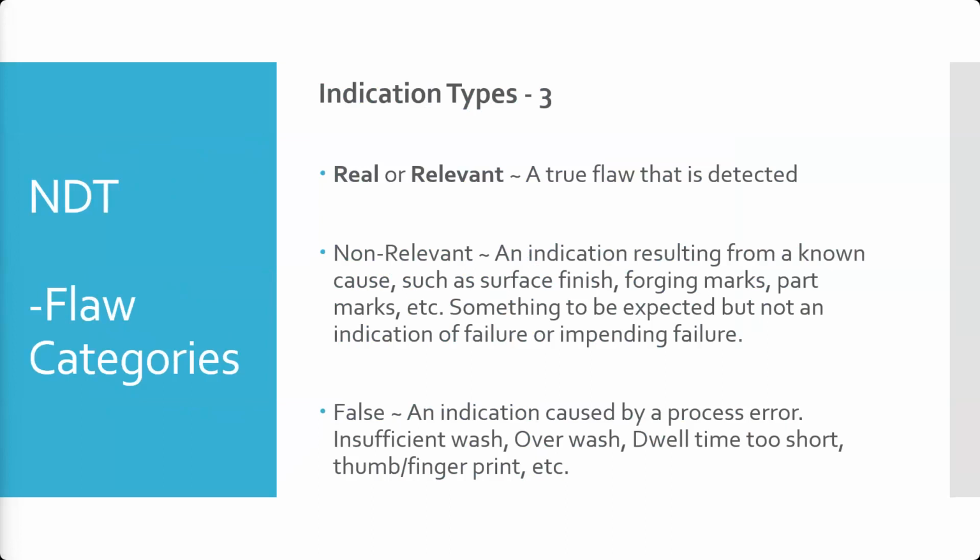For aviation, the determination we're typically making is, is a part serviceable? And the key word there is serviceable. Serviceable means it can be installed on an aircraft. Parts by themselves are not airworthy, right? The aircraft as a whole can be airworthy if it's made up of serviceable parts, or if you have the ability to defer maintenance on non-serviceable parts. But ultimately, that's kind of the real difference.